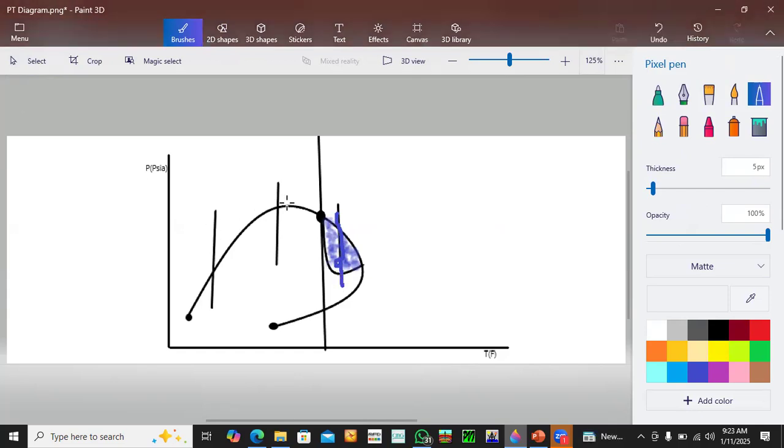That's the difference with the other kinds of fluids. So as pressure depletes from initial reservoir pressure, upon reaching the dew point pressure, we start dropping liquids, which we call condensates. It continues dropping condensate liquids so far as the pressure continues to deplete within the retrograde region, but upon exceeding the retrograde region as pressure depletes, what happens again? It starts reversing back to its gaseous state.